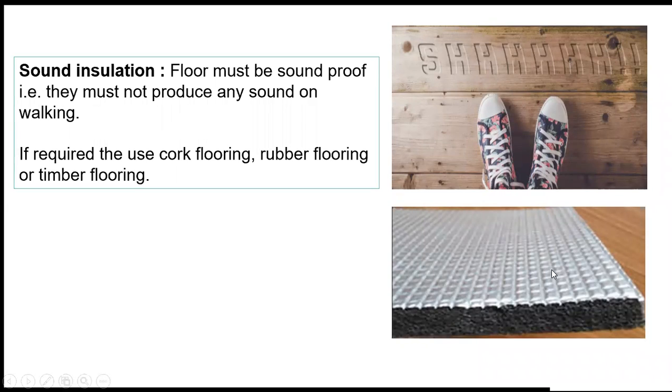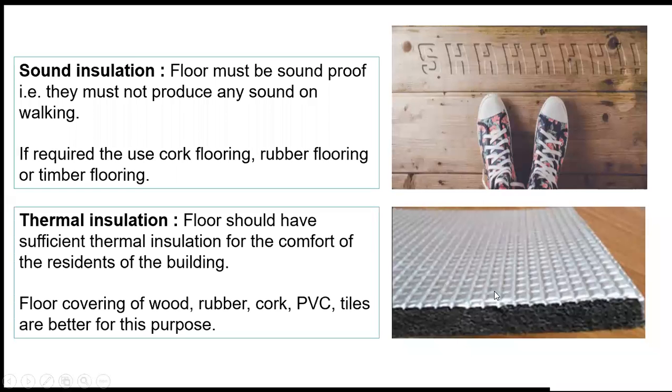Now, if you see another picture in the bottom right, thermal insulation. The floor should have sufficient thermal insulation for the comfort of the residents of the building. If your floor is not thermally insulating, then in regions where the day temperature is very high, your floor will not be comfortable for the residents. For floor covering, wood, yes, everybody knows wood is a thermal insulator, as are rubber, cork, PVC, tiles.